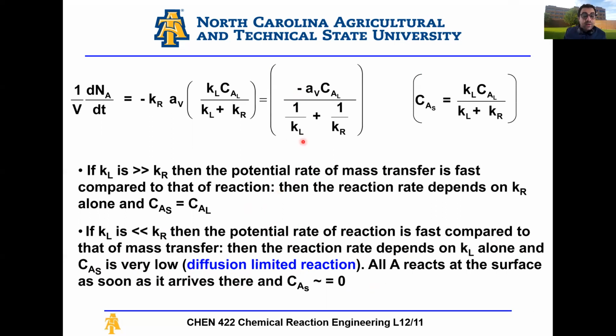And depending on the nature of your process, you need to identify whether it's mass transfer limited or reaction limited, and then this will be the starting point to guide your practical design of the reactor, whether I want to have mixing, how important is mixing to the process, all of these details.